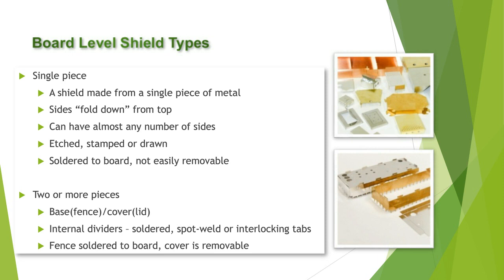or if you have a large shield with a lot of parts that you're going to try and wave solder at the same time as you solder the shield down to the board, sometimes it's difficult to get heat under the shield. So you have trouble reflowing the components underneath. Sometimes people put cooling holes in the shield to accommodate for that. The photograph at the top on the right shows some shields with cooling holes.